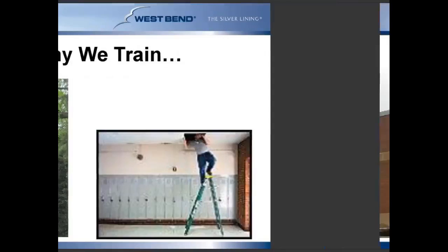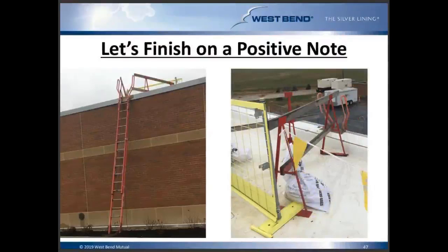So with all those horrible pictures that we just saw, I want to give us a palate cleanser here and see if we can finish on a positive note. These were 2 pictures that one of my colleagues had taken at one of his customers' roofing job sites a few weeks ago, where we have an extension ladder set up. I don't see any cause for concern for any cars, equipment, or people running into the base of that ladder. From what I see, the angle looks to be at the 4-to-1 ratio that we need.